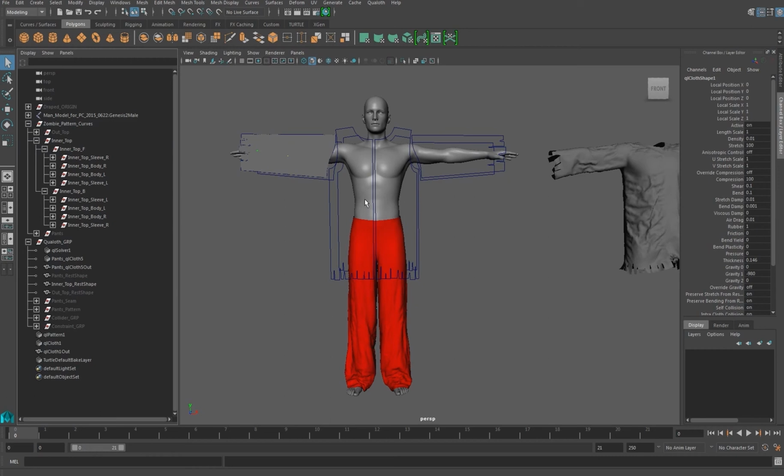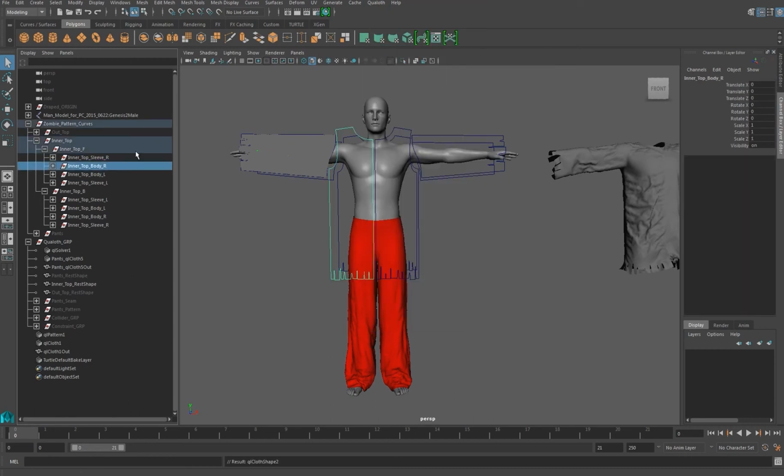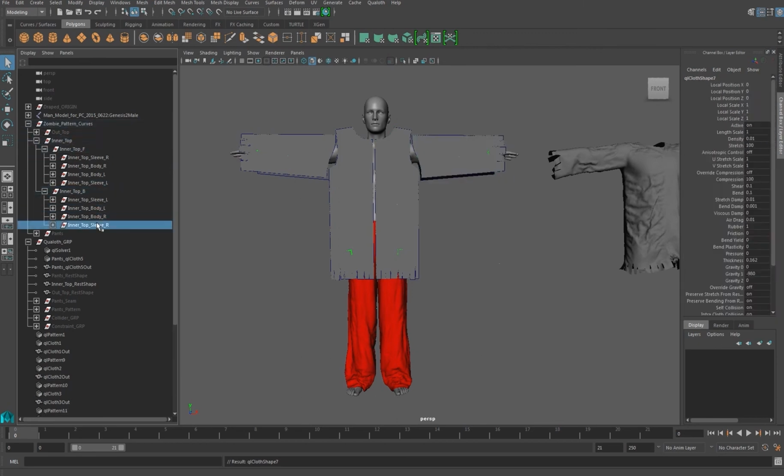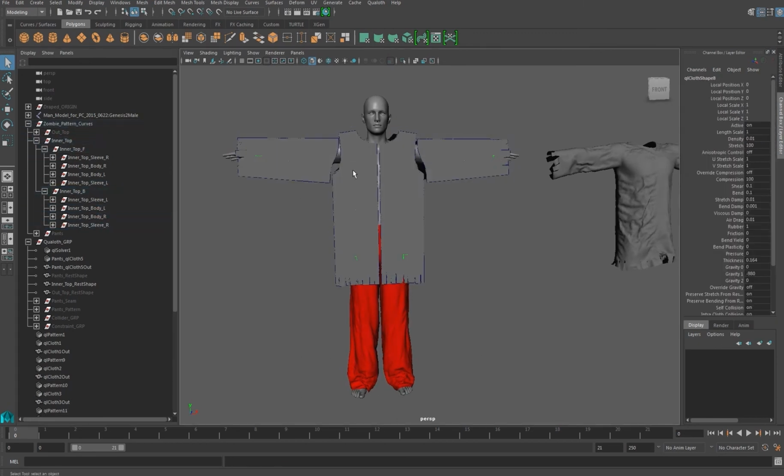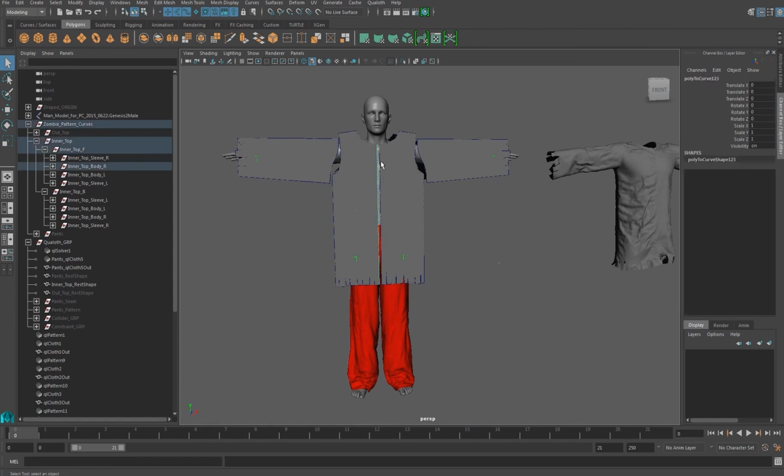With that, we can simulate with just one solver for multiple layers of costume. It will manage to calculate self-collision that occurs in multiple costumes to each other automatically. Furthermore, this workflow allows us to use the trouser's collider setting that was made beforehand. There is no need of adding collider on inner cloth. With the same procedure, create the rest of cloth. When you're done creating the costume mesh, select the pattern curves that face each other. Click on Create Seam command, so it becomes a part of costume mesh.